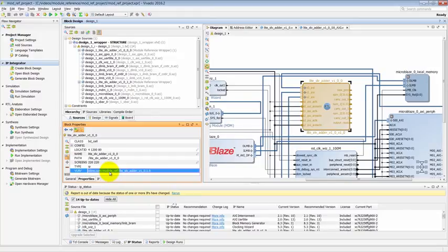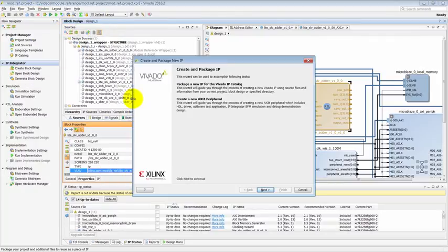So now you have an RTL module that has been instantiated in a block design and has been verified. Let's say you want to then share this with other members of your team. One way to do this would be to hand over the entire RTL code, which would then have to be included as a part of a new project, and then the module instantiated, as we have learned in this quick take video. The other way of doing that would be to use the packager flow and package the IP. Once the IP has been packaged, it can be reused by other members of the team easily. This flow is described in another quick take video called Packaging Custom IP for using in IP Integrator. Please watch this video for more information.